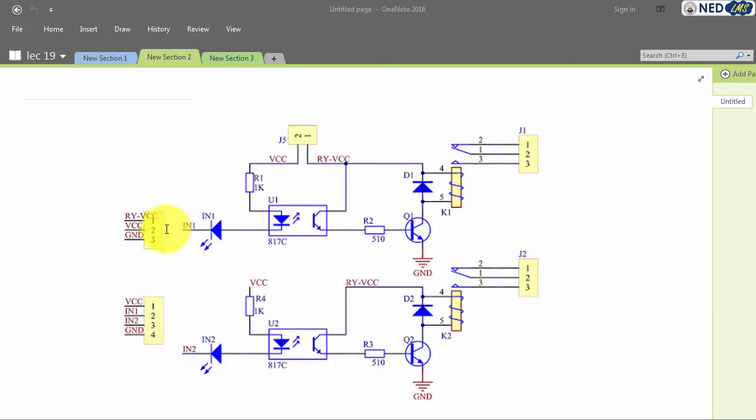So the Arduino output is actually active low, which means it's inverted logic. So to output high, we set the output to low, and when the output is set to low over here, this circuit is enabled. A 5 volt signal will come over here, and if we have a ground connection, the output is set to low, which in Arduino means it's high. It's inverted logic. You will understand because it's actually sinking current over here, not supplying current. So it's just providing the ground path over here. So the 5 volts will forward bias, or just turn on, this LED as well as this LED.